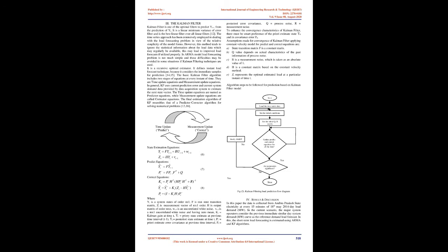B. The moving average, MA, process. Simple moving average is the most basic of the moving averages used for short-term load forecasting. The moving average is also defined as rolling average or running average. It is a calculation to analyze data points by creating a series of averages of different subsets of the full data set, which depends on the order of the MA process. The order of MA is denoted as Q.